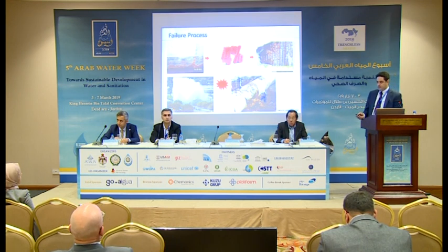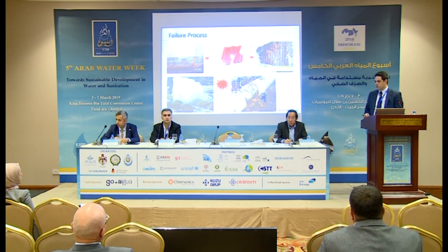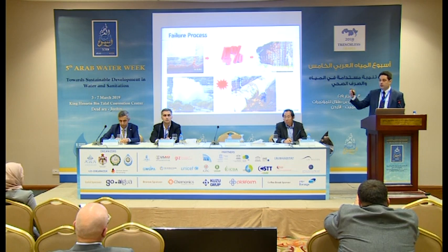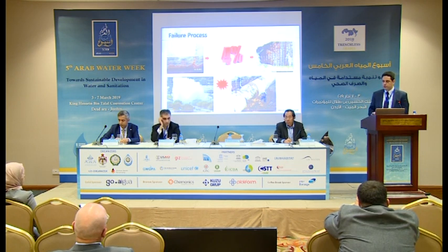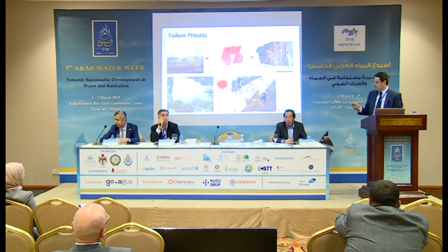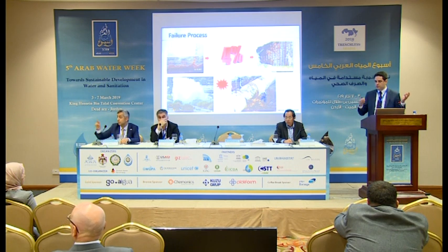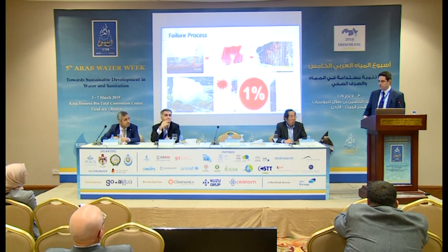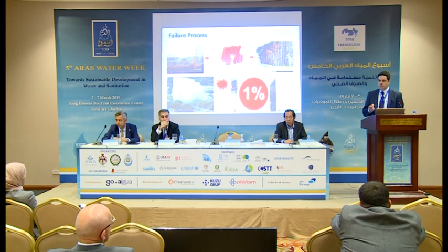The good news is that in a given concrete pressure pipeline, the number of pipes that in fact are degraded and therefore potentially in need of rehabilitation are limited to 4%. That covers statistics from previous inspections of pipelines. And another good news is that among those 4%, if you analyze them in detail, the ones that are actually in imminent danger of rupture are about 1%.